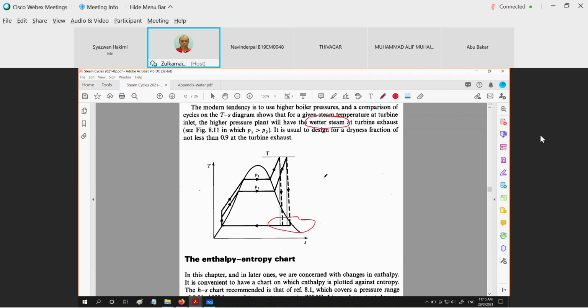It chips off. Okay, the turbine blade is chipped off. So if the turbine blade chips off, it means there is a hole in the turbine blade. When we inject the steam through the nozzle, this hole will become bigger and bigger and bigger. Eventually our turbine blade will fail, the whole turbine will fail. It's very dangerous. So we try to avoid this part.